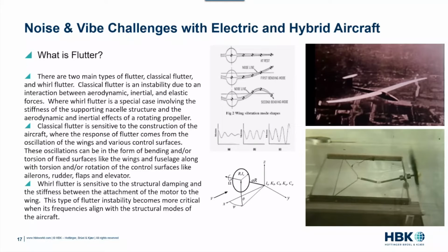First, some of these things are well defined from a certification standpoint. One of those areas is flutter. There are two different types of flutter. There's classical flutter, which is basically an instability due to the interaction between aerodynamics, inertial, and elastic forces. But then there's whirl flutter, which is sort of a new beast in a way. It used to be